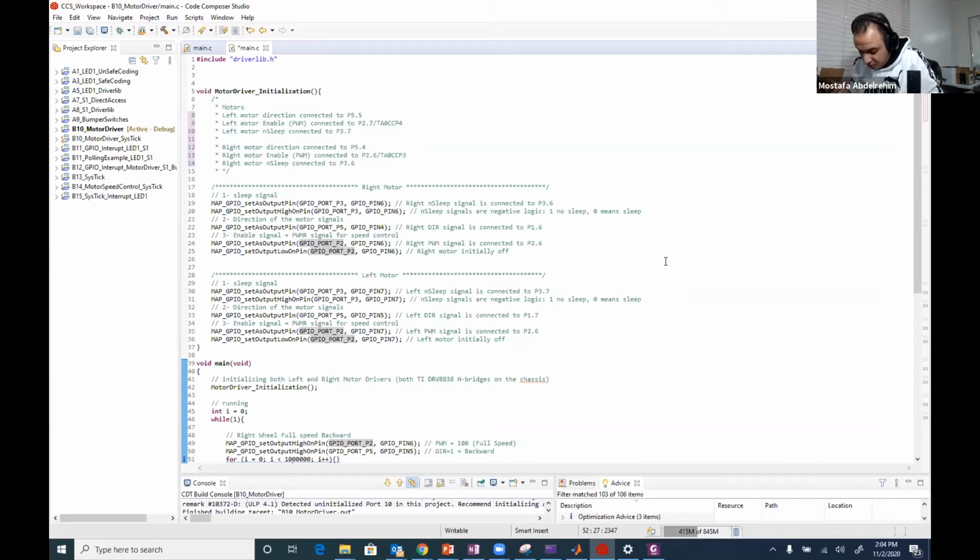Guys, remember if you're going to buy Energizer batteries, buy the one that is 1.5. This is 1.2. I don't know if you can see this. Okay, it works, but some LEDs on the chassis board itself will not work. But it will run the motors. So if you're going to buy an Energizer, look out for this. Buy something that is 1.5, not 1.2, like this one.